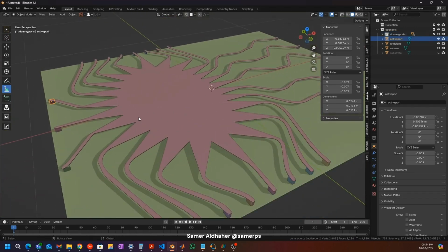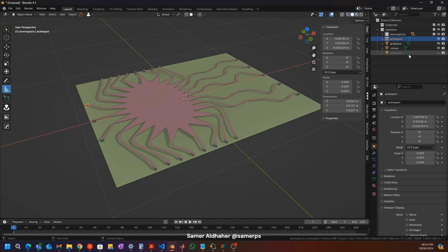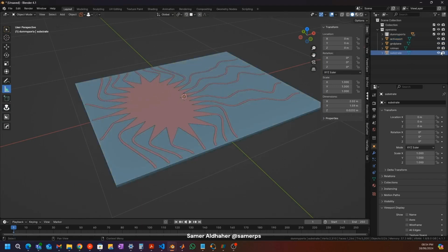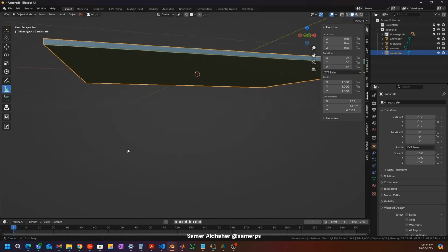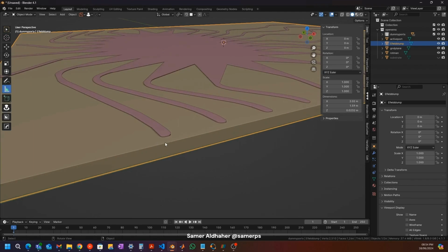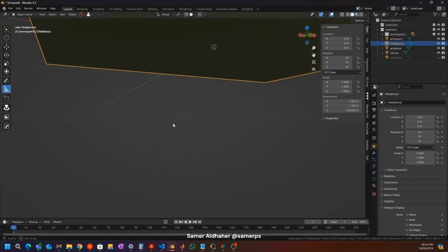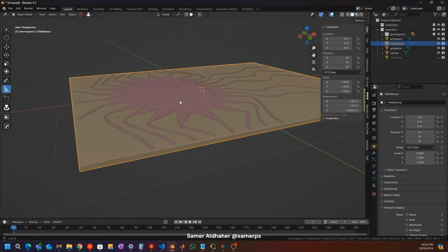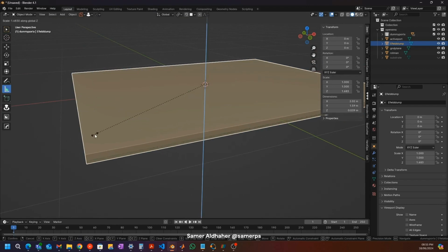And finally, we need to define our E-field dump box. So what I do is I just take the substrate, duplicate that, and call it E-field dump. I basically want to capture the E-field not just in between but also slightly above and below the copper. So I'm going to scale this.